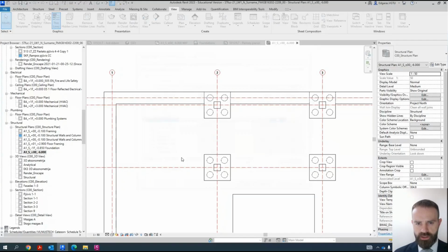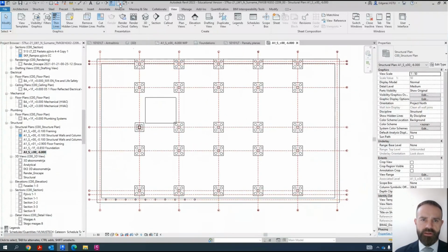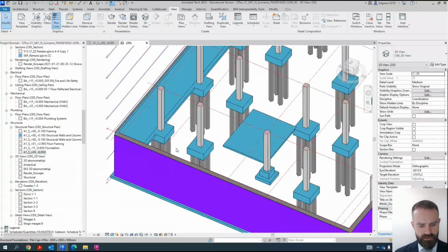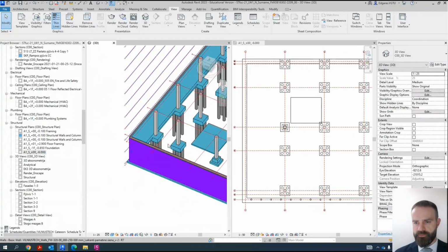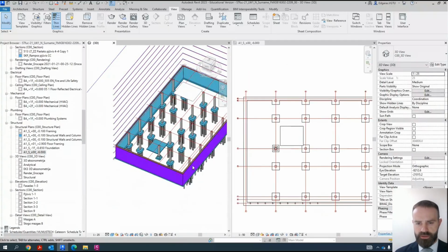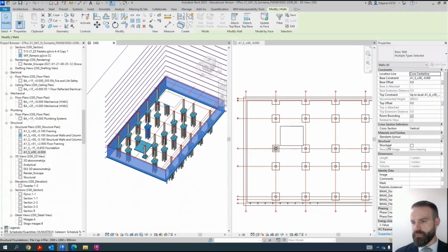Walls, okay. So I don't see walls because walls are not structural elements. And I need to go to my 3D model and do the modification, so you can see what will happen. So I select all the walls around my building and put the check mark on Structure. And in the location, I click Bearing and apply.